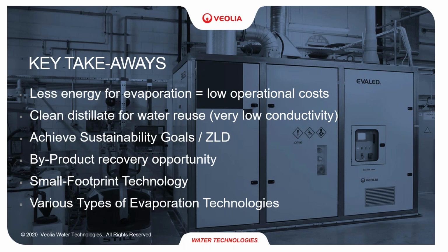And to know that there's various types of evaporation technology. So if you have a cogen facility on site, we may be able to look at using some of your waste heat. If you have a smaller flow, we can go more with those heat pumps. And if you have a bit of a larger facility, then we can go with more of those mechanical vapor recompression. All standard products, standard models, so we can really find something that's fitting inside of those windows.